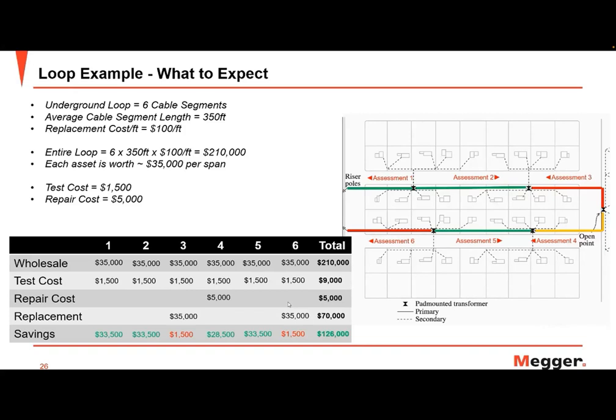Resource utilization. If a utility can bore in just a certain amount of cable per day, then in this particular case, in the proactive solution, you're only boring in 2 cables versus 6. So we're saving time with crew days and crew costs. We've got the investment return there, $14 for every dollar invested. But the main thing that's going to happen here is because we've got the same result, a defect-free cable system, we're going to improve the reliability of the whole system.